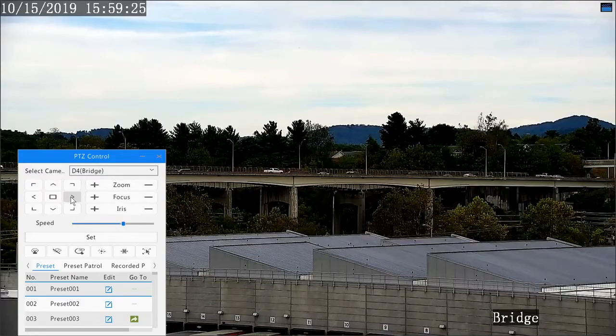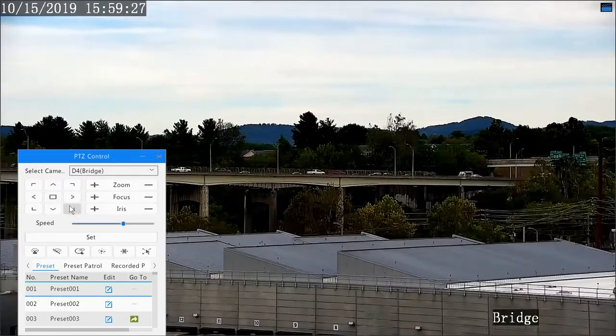Oh, great. And I think, James, you had spoken to it earlier, but with PTZs, you can control them locally, right? Like at the recording device itself. And do you do that via a mouse or a joystick? How do you actually interact with the PTZ? Yeah, so you basically control it there. You bring up the PTZ control option, and then you'll have a virtual joystick.